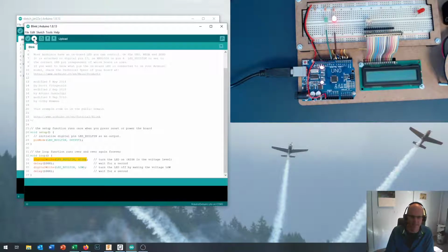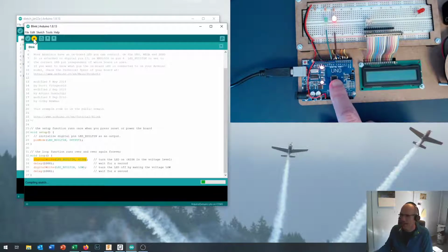And because we shouldn't have touched anything or edited anything, down here it says Arduino Genuino Uno on COM3, or maybe COM27 or whatever the Device Manager told you your COM port was. And then you're going to click on Upload. And when that happens over here, you should see a little bit of, just a minute, things are going on right here.